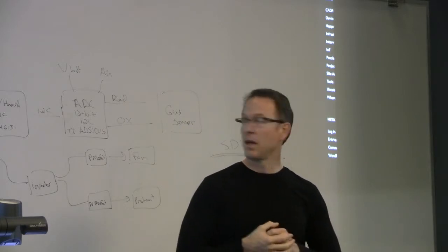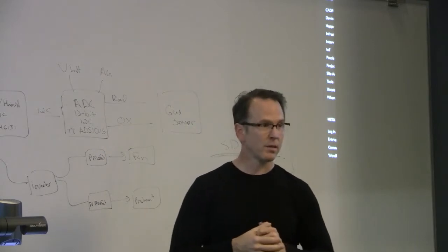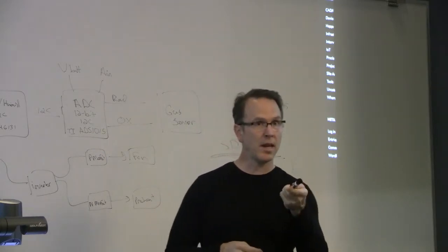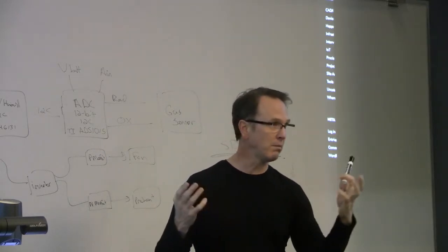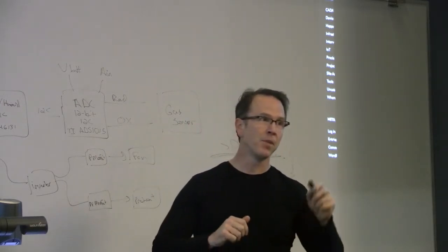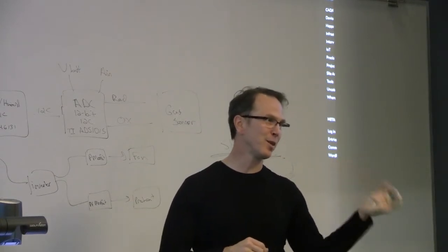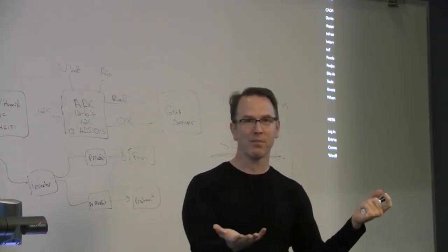What's the number of that? That's a PCA9306. Is that a surface mount? It is. And now here's another mistake I made, because I make a bazillion mistakes. It comes in 2 sizes, and I ordered the chips in one size, and I put the footprint on the board in the other.